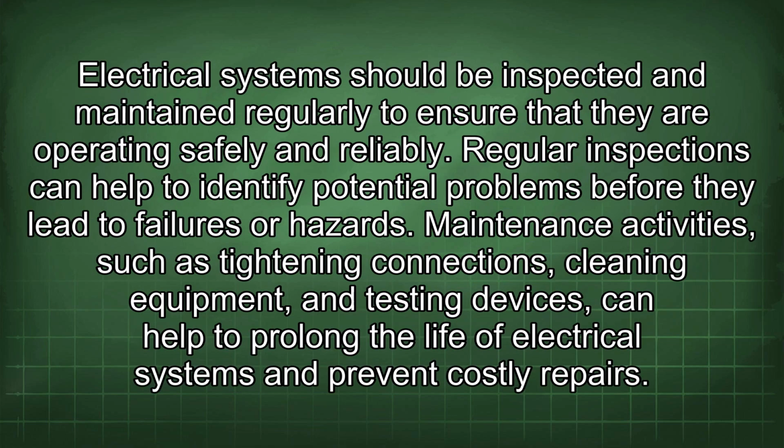Electrical systems should be inspected and maintained regularly to ensure that they are operating safely and reliably. Regular inspections can help to identify potential problems before they lead to failures or hazards. Maintenance activities such as tightening connections, cleaning equipment, and testing devices can help to prolong the life of electrical systems